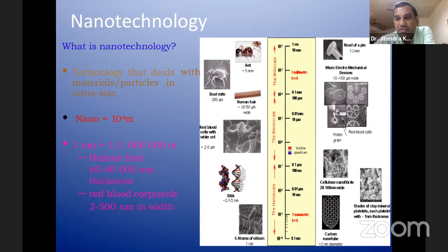And here there is much tribological behavior. When you move to the nano scale, adhesion increases, so the friction on the surface also increases. So take care that when you move smaller, adhesion also increases, and van der Waals forces are also improved. Because of that, nano tribology is very important in these aspects. Tribology is nothing but the study of friction and wear in various environments.